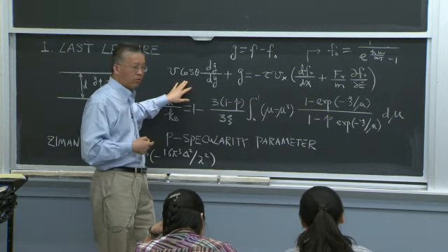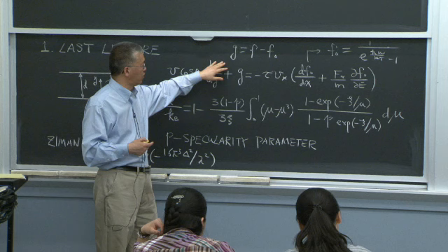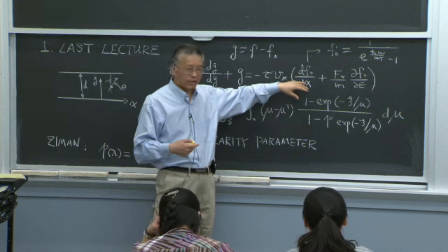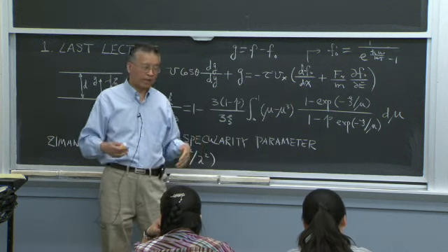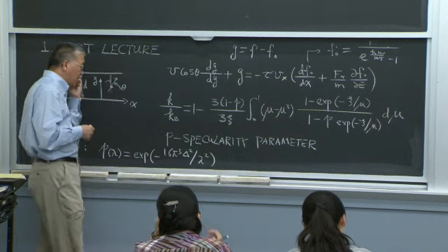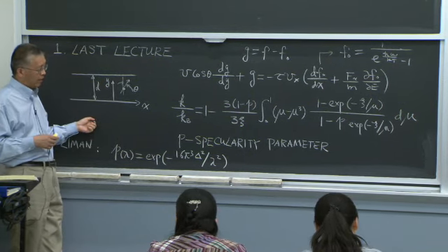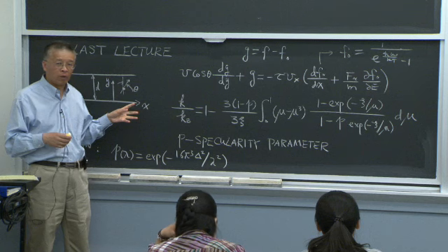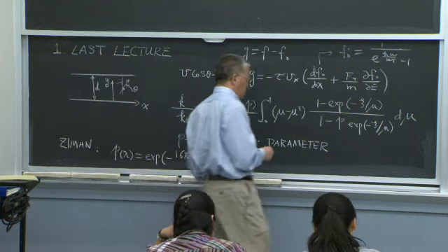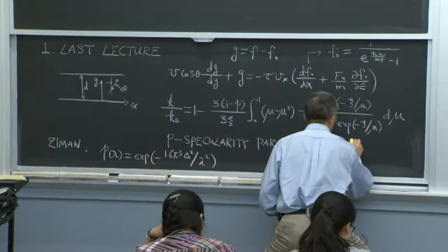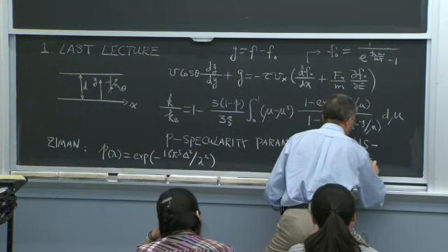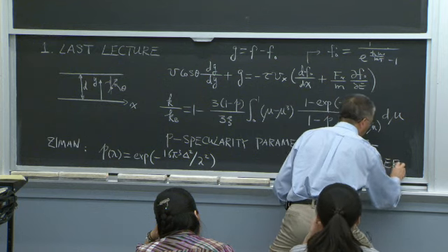So I have a first-order differential equation for the deviation function in the y direction, with a right-hand side that is x-dependent. Because the left-hand side is a function of y, the right-hand side is essentially constant. So when I did the integration, I found the heat flux. And what I'm giving here is more than I showed in the last lecture, because this solution is the Fuchs-Sondheimer solution.